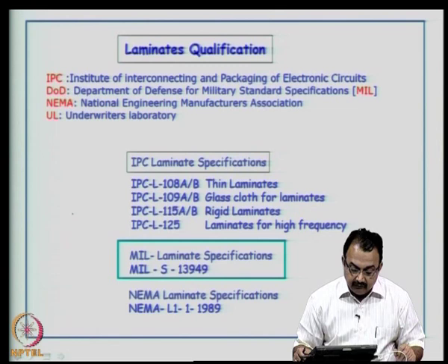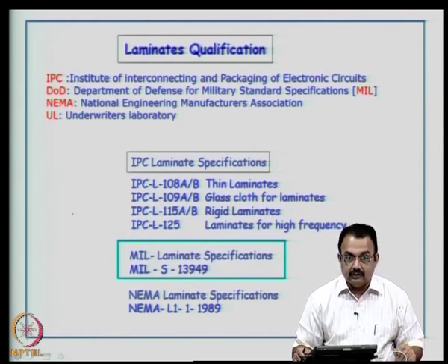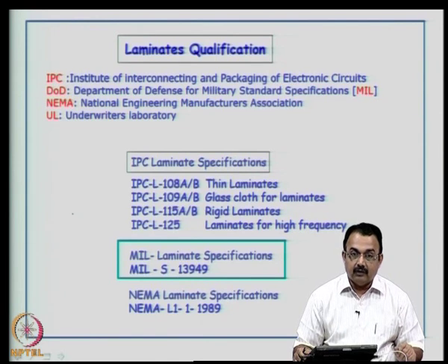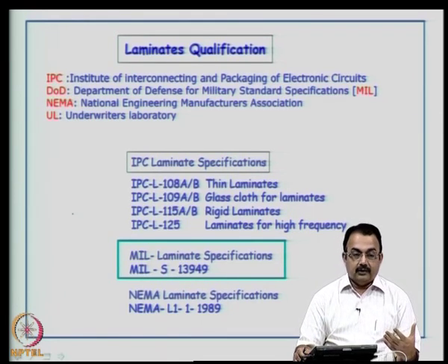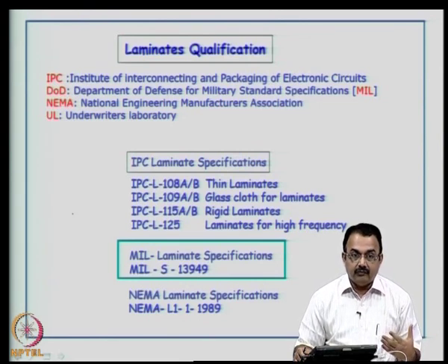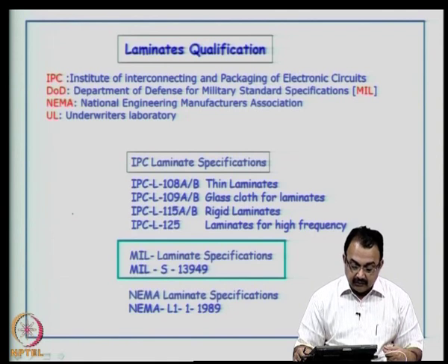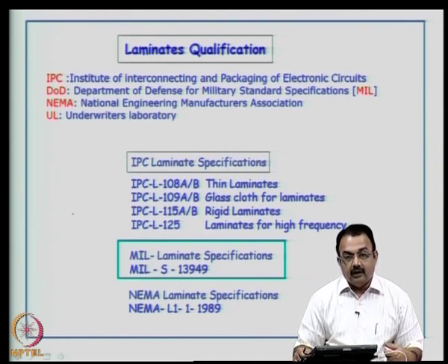Now, the Department of Defense military has also brought out mil standards for laminates qualification. So, if a company A produces these laminates, they have to follow some of these standards like the IPC, the mil standard, or the NEMA standard, that is National Electrical Manufacturers Association, or the Underwriters Laboratory.